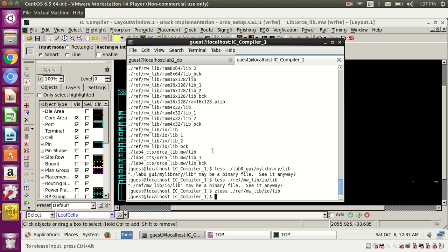I'm saying that statement. So when the inputs are changing, the data path has to change. That is the thing. Then why is it not changing? It is because of our constraints. So the main input of clock gating is our constraints. Set case analysis, false path, all those things will be there. Set multi-cycle path, all those things.